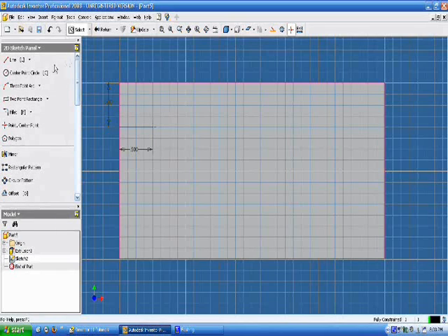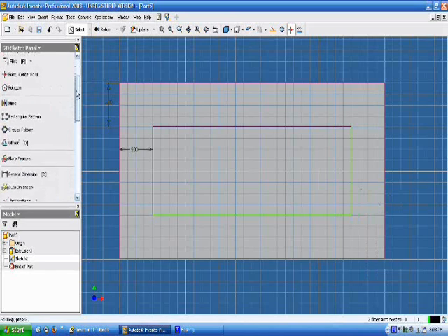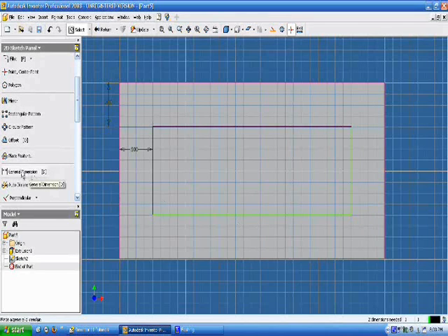From this point is where we're going to be creating our rectangle. So let's click on 2-point rectangle here. And see how that little green dot shows up in the middle? When that's visible, you just click with your cursor and just pull down as such. Click done. And let's dimension this one, these sides.